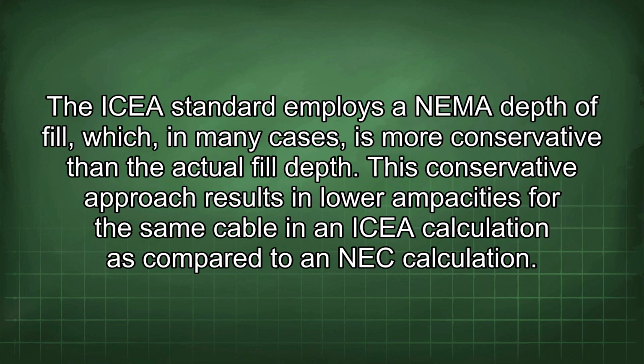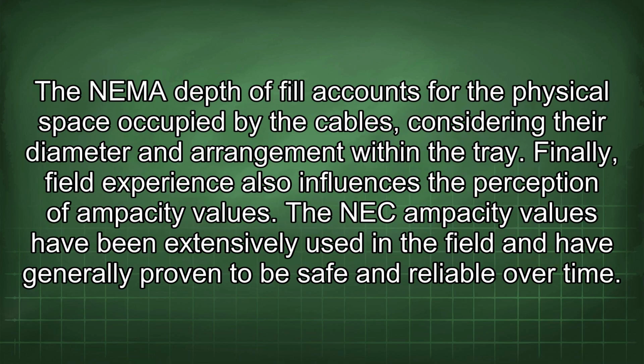The ICEA standard employs a NEMA depth of fill, which, in many cases, is more conservative than the actual fill depth. This conservative approach results in lower ampacities for the same cable in an ICEA calculation as compared to an NEC calculation. The NEMA depth of fill accounts for the physical space occupied by the cables, considering their diameter and arrangement within the tray. Finally, field experience also influences the perception of ampacity values.